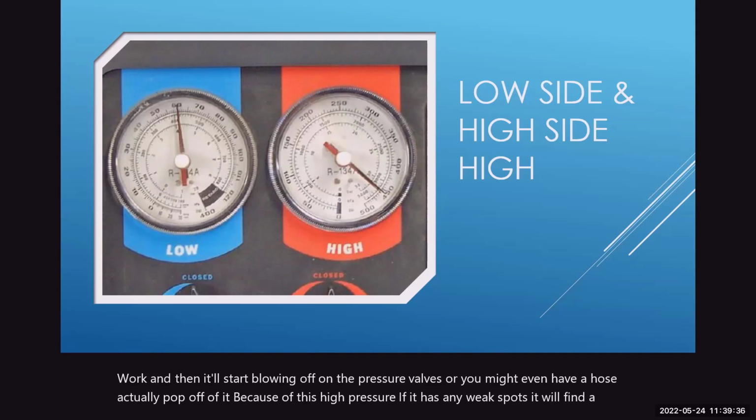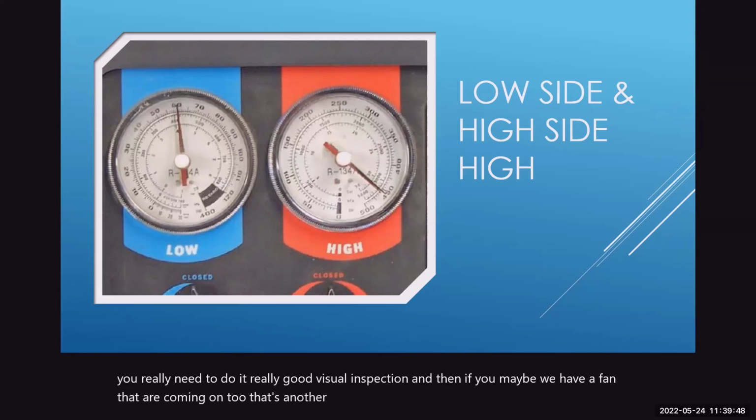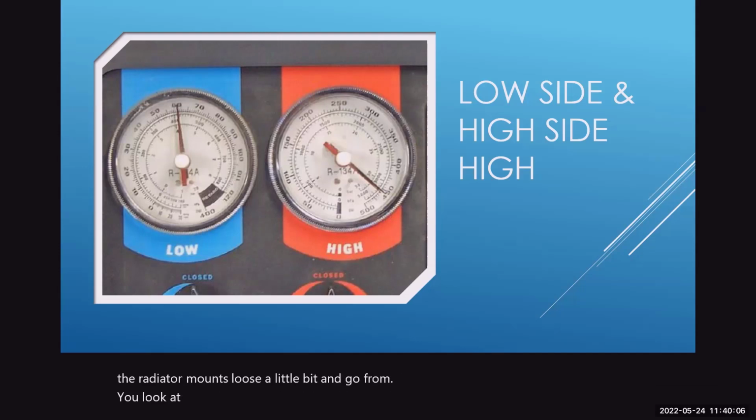So you really need to do a really good visual inspection, and then maybe we have a fan that's not coming on too. That's another possibility. But if it's restricted, you can take a nice garden hose and clear it off. You want to go reverse on it. You don't want to do the airflow side. You want to take the radiator mounts loose a little bit, look at the airflow coming in, and then go the opposite direction with the garden hose.